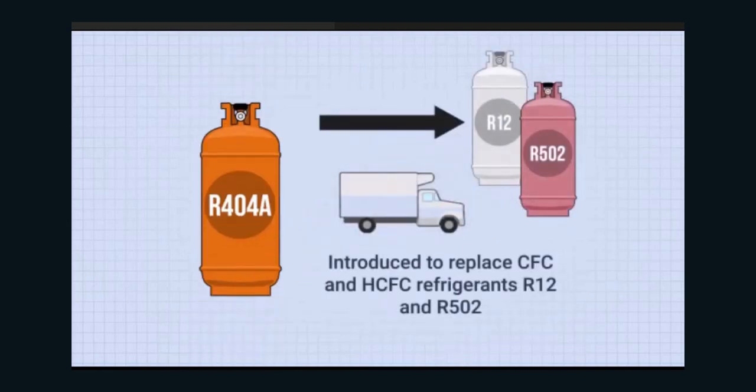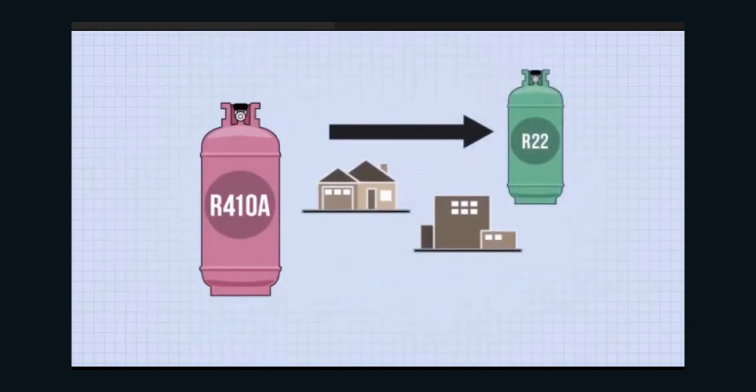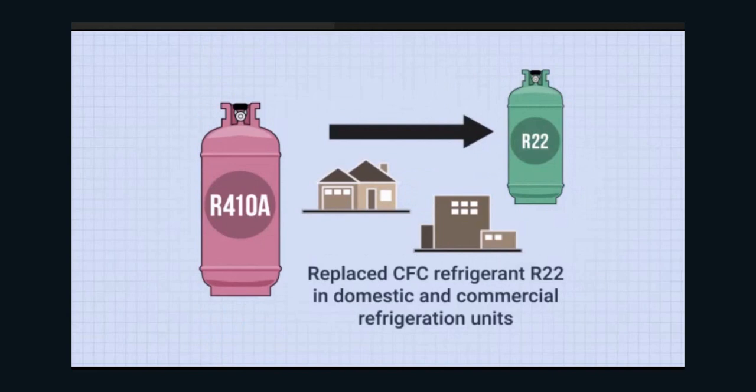R404A, introduced to replace CFC and HCFC refrigerants R12 and R502, used widely for transport and supermarket refrigeration, also for cold storage and industrial refrigeration. R410A, replaced CFC refrigerant R22 in domestic and commercial refrigeration units.